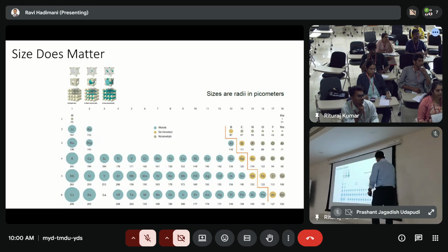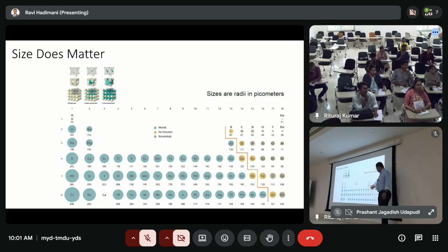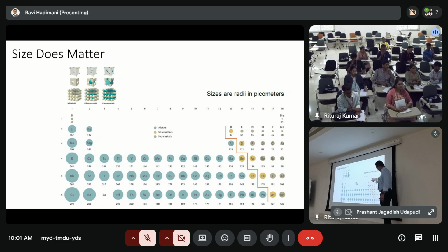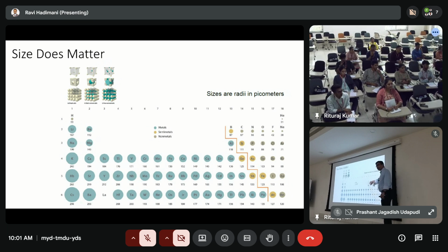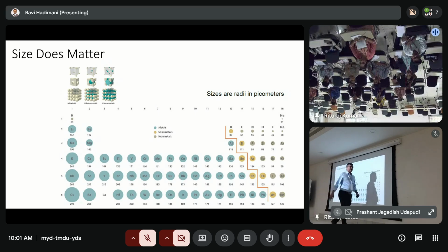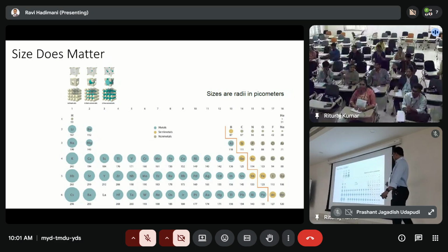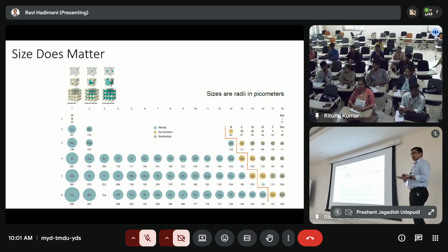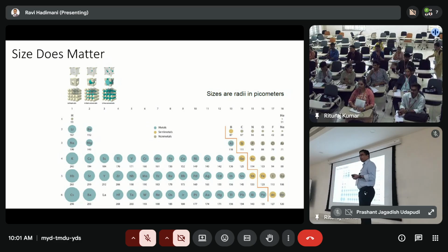Okay, silicon is the most preferred, but if you use a silicon wafer, you are restricting yourself to only some of these atoms here. So you have to move away from silicon wafer if you want to use hafnium, tantalum, tungsten, or platinum, gold. You have to match the atomic radii between the substrate and your deposit.